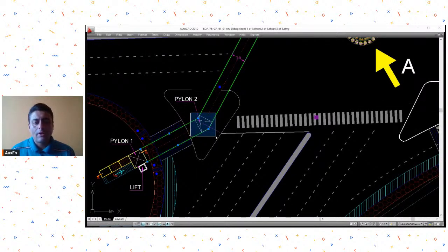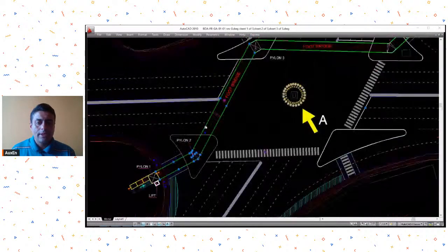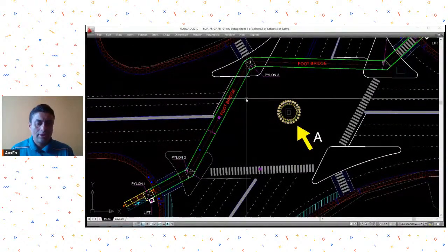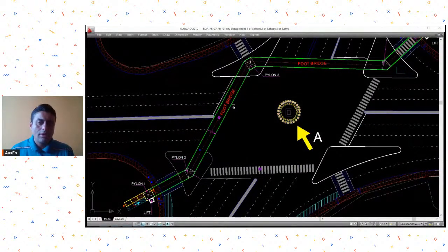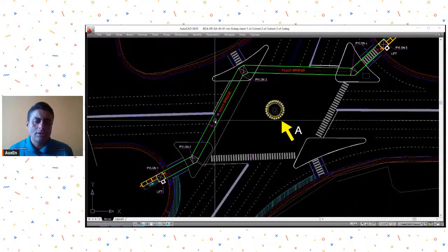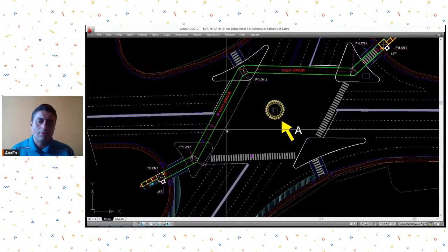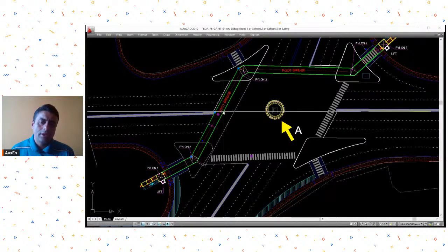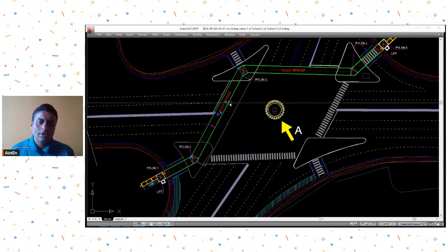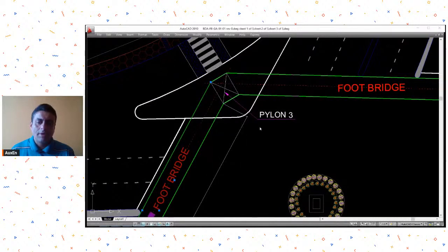They have written pylon, it's a column support. Then comes the main span, from here to here. I think it's almost 40-45 meters. This was a scale of 3, so it will come out to around 45 meters. This will be across the road, with the road below. Then you come to the next traffic island. Here again there will be a pylon supporting system.